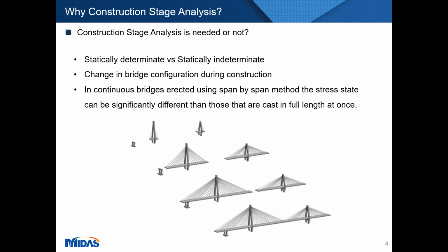As you can see, there are various steps involved in this construction method. So when we model each and every step of this construction in the software and we analyze each and every step, that is called the construction stage analysis. Now that we have answered what is construction stage analysis, we also need to ask the question, is construction stage analysis needed or not? To answer this question, we need to look at certain conditions.